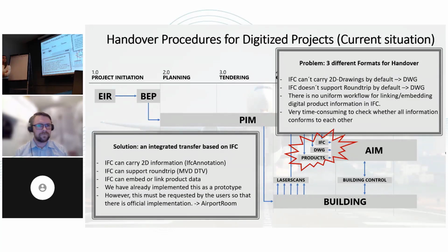Maybe to explain the round trip: it was meant that when we are going to operate buildings and we want to rebuild the buildings 15 years later, as you said, native formats are not useful for that. They're not working anymore in long-term thinking. For that reason, we thought that if we carry rough information about the facilities in IFC, it's possible to have more or less standardized round-trip functionality to rewrite or to make IFC files editable later on.